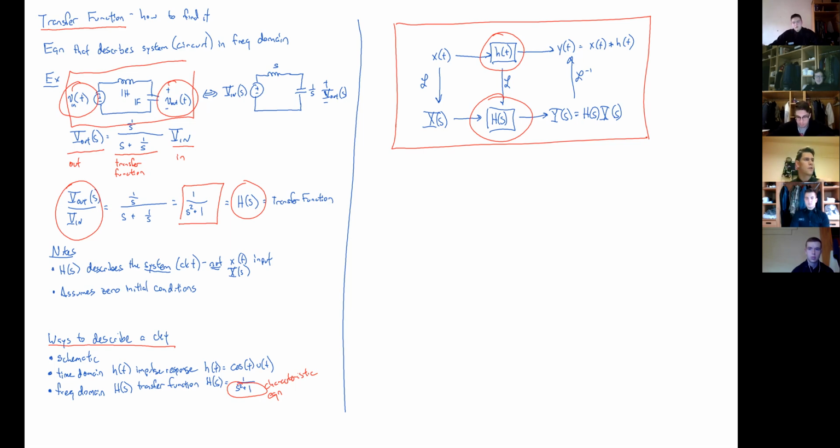All right. Sir, I have a quick question. Shoot. Just about what you wrote. This diagram is really important, so ask the questions about it. Right. So the y(t) over there, you said it's equal to x(t), which is not equal to h(t). Is that what that's written? So h(t) is definitely different than x(t). x(t) is our input. h(t) is our system. And y(t) is another signal. And it's equal to our input convolved with our impulse response. Oh, that's an asterisk. That's what it's supposed to be. Okay, right. Thank you, sir. Yeah, sorry about that. No wonder that was confusing.